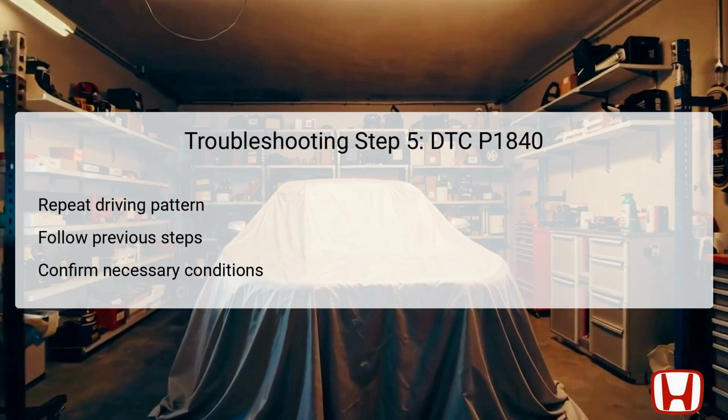The final troubleshooting step involves repeating the driving pattern outlined in the previous steps. It's important to follow the sequence carefully, ensuring that all conditions from the earlier steps are met again. This repetition is crucial for confirming whether the original DTC P1840 persists or if it has been resolved as a